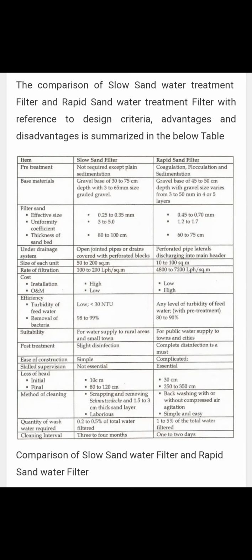So that process is simply the settling type, or sedimentation type 1, or you can say plain sedimentation. And type 2, the second type, is sedimentation with coagulation. Plain sedimentation has various advantages. What are the advantages of plain sedimentation? It removes 60% of the solids. Also it removes various percentages of bacteria from the water. Also it reduces the cost of the treatment, and it minimizes the amount of coagulant required for the chemical coagulation process.